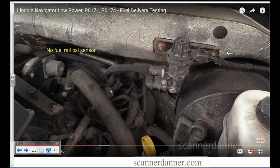So no fuel pressure sensor, that means it has a regulator. Regulator's in the tank on this one. That unusual one I described to you guys in chapter 14 with the regulator in the fuel filter, Ford doesn't use that. All stuff we want to know. Research and experience will teach you. That'll be your guide. Next page.